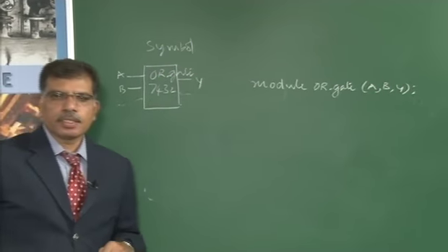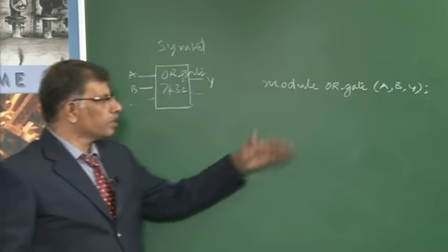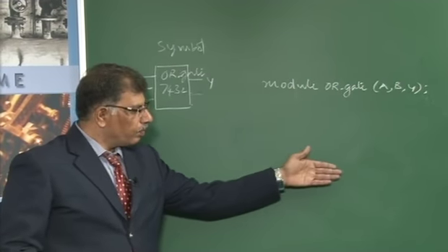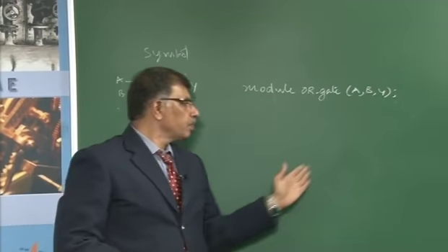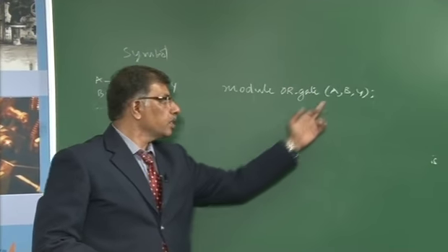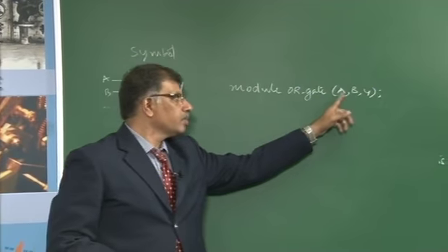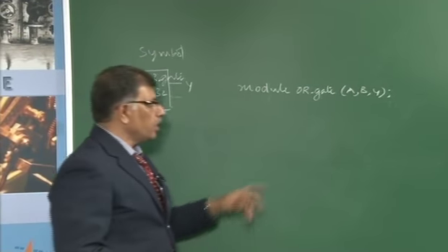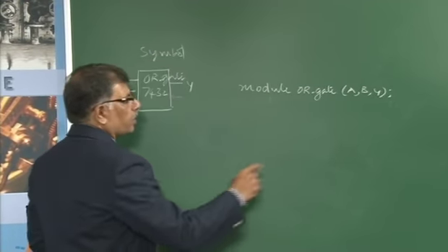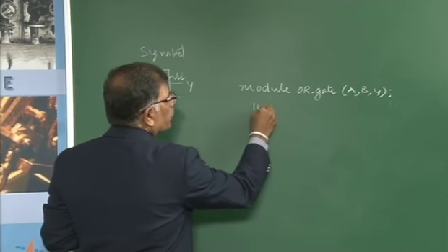See, Verilog is case sensitive. While referring to the names, or while using the inputs and outputs in the functionality description, the same letter case should be used. If you use a small case, it will not identify it and will give a mismatch or something like that. So now you have to define the inputs here.